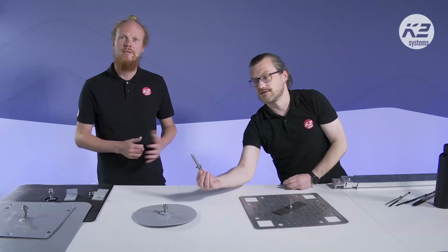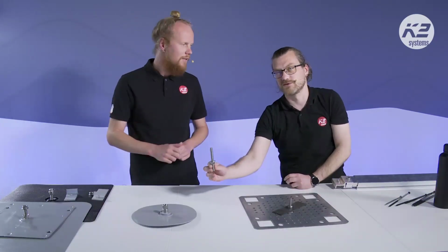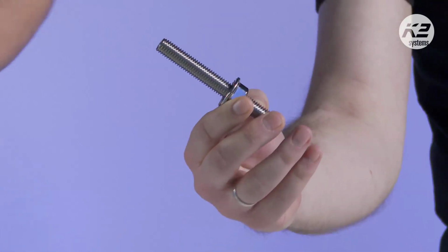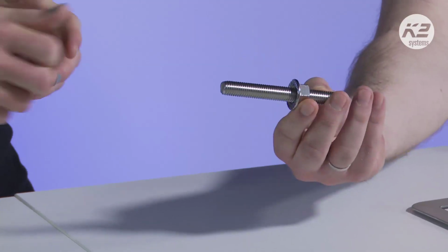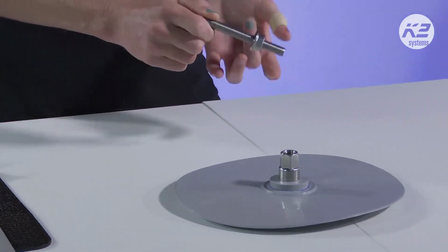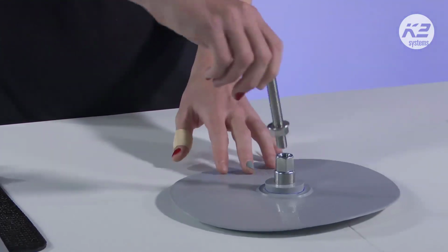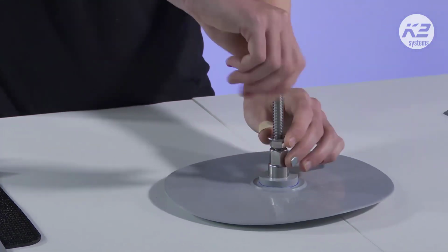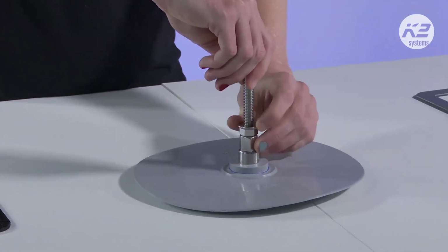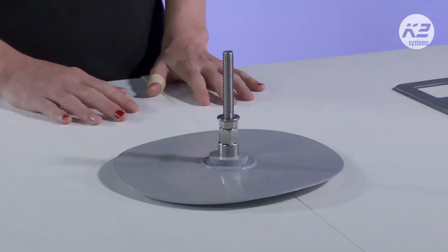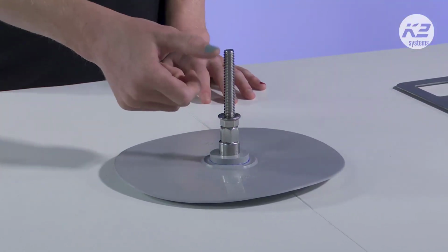It comes in 3 parts actually. Exactly, it comes in 3 parts. It's a leveling set from Sika. Just take care that if you're ordering anchors from Sika, you also order this leveling set. This allows you to have different heights. As you lower this, you're going to screw it into a different height, and therefore it allows you to get a higher bolt. And if you have any unevenness in the roof, you are able to compensate for that with this height here.